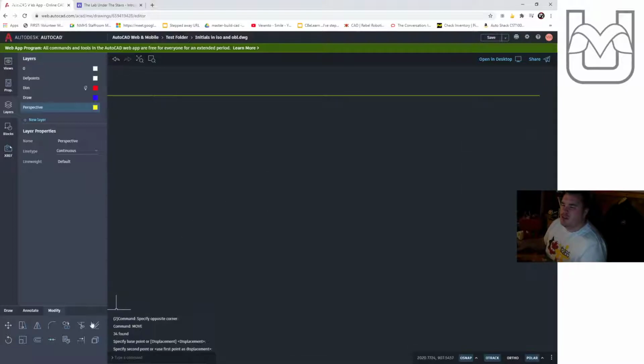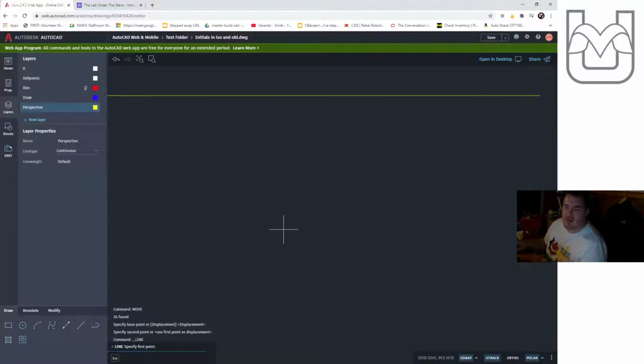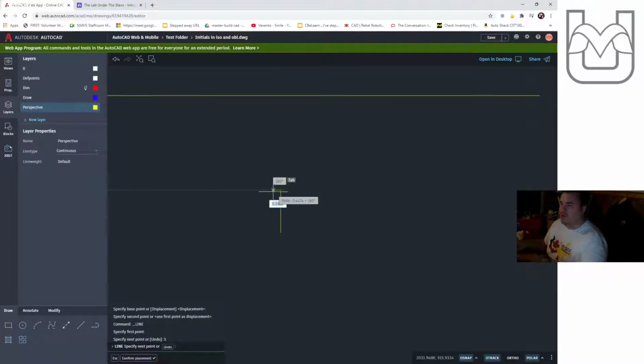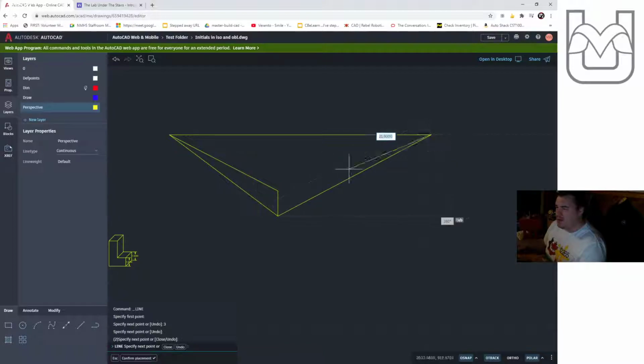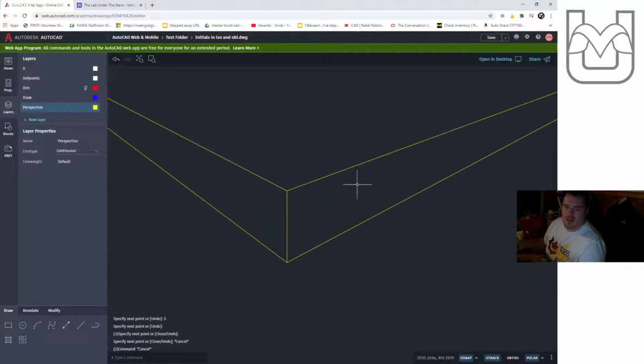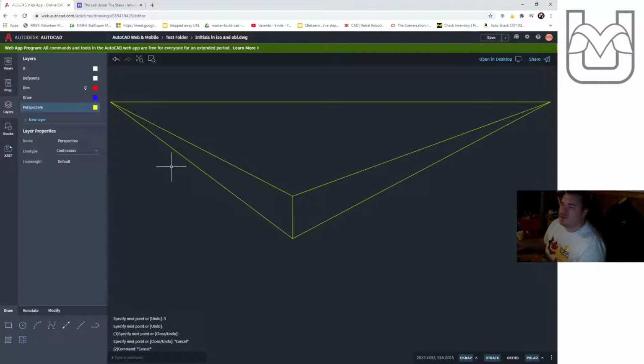Now, just like we were talking about with an isometric drawing, we are going to start in the vertical here. And we're going to start with a vertical line. And unlike the 1-point perspective, I do something a little bit different here. 2-point perspective is relatively easy to get started. You just run both sides off into the vanishing point. That's our X and our Y direction. Our X and our Z direction.